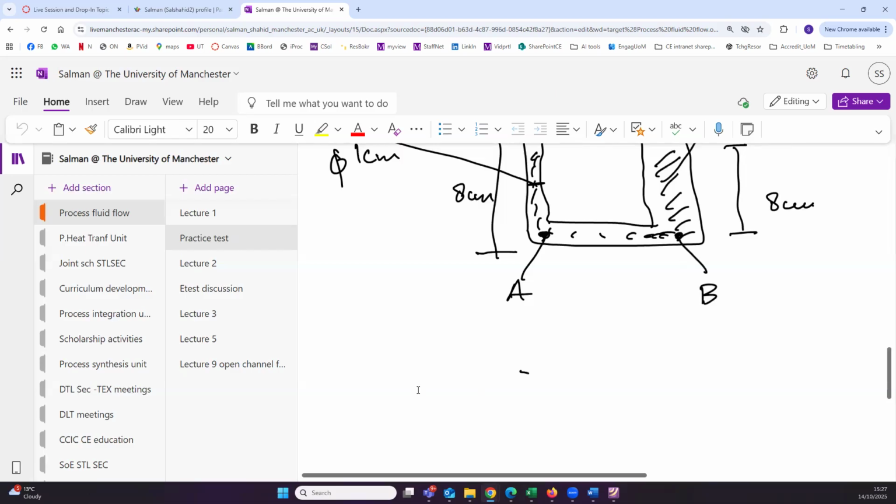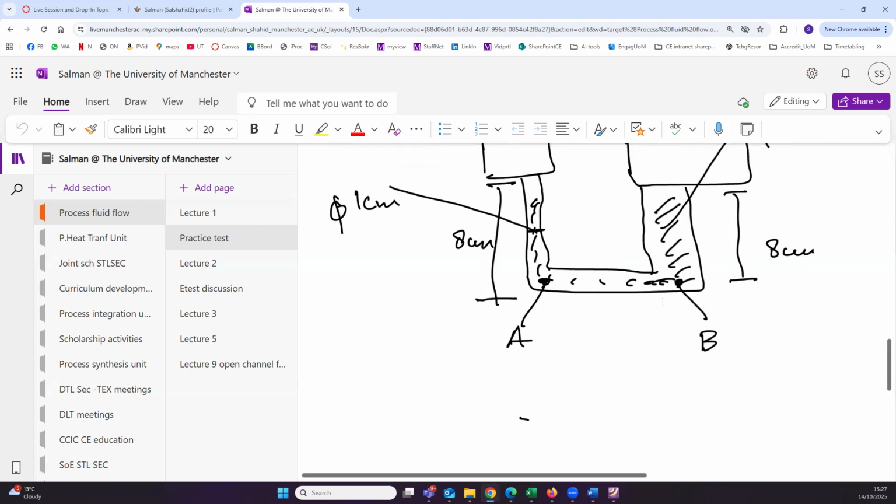If you go 10 meters further down, you will have 2 atmospheres, and if you keep going, let's say 5 times 10 meters down, you will have 5 atmospheric pressure. So it doesn't really count the surface of the sea, it just counts this height. And that's the same principle that you will use in this example. So do not worry about the shape or the size of the thing, just think about the height. Okay, the next question is